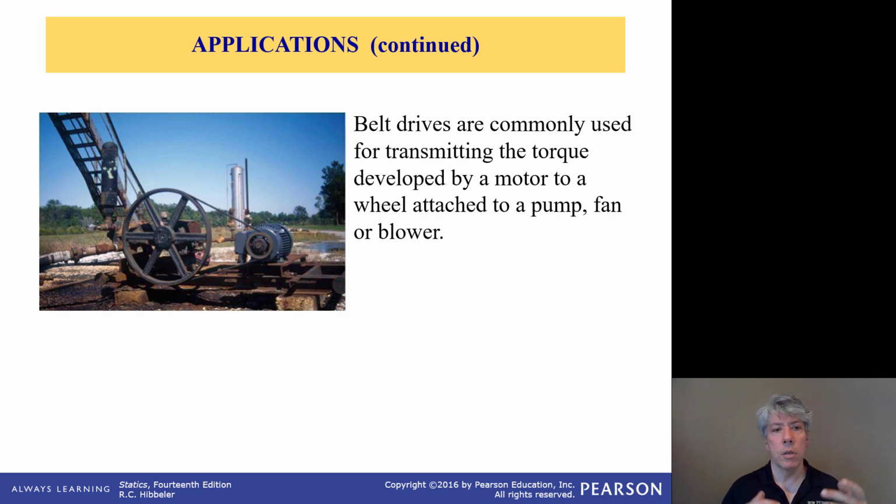Anyway, so when we have a machine set up like this, one of the reasons for using a belt, by the way, is the belt is somewhat forgiving. If the machine chokes or locks up where it can't turn, the belt can actually slip, and that doesn't damage the motor as badly if it's not noticed immediately. If you have a motor and the rotor is locked and it can't turn, you're applying current to that motor, the motor will burn out pretty quickly because all the energy goes into the motor and just turns into heat rather than into mechanical work. And so it overheats the motor.